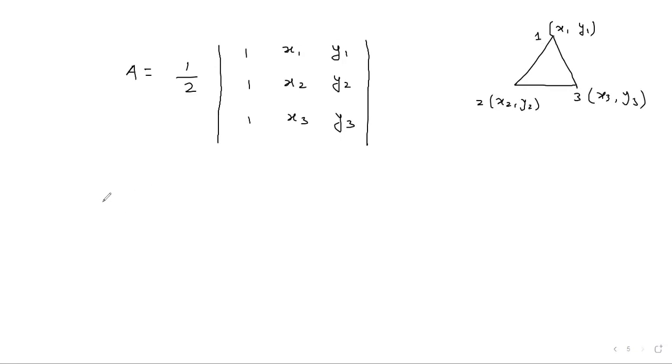Now coming to the B matrix. This is very, very important. You can find this matrix while deriving the shape function of the CST elements. We have discussed this B matrix, that is 1 upon 2A into: beta 1, 0, beta 2, 0, beta 3, 0.